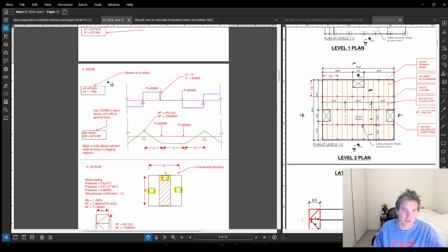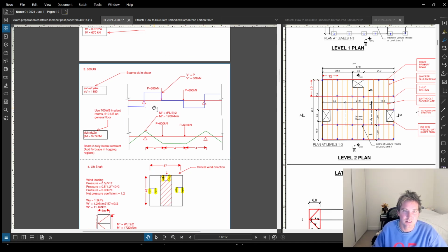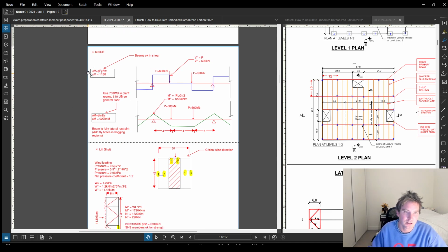Have some basic calculations, but also these bending moment and shear diagrams, which really illustrate my understanding of the design of the beams and the load path. How's the load getting from the secondary beams back to the supports, and that's what I am intending to do with these shear and bending moment diagrams.